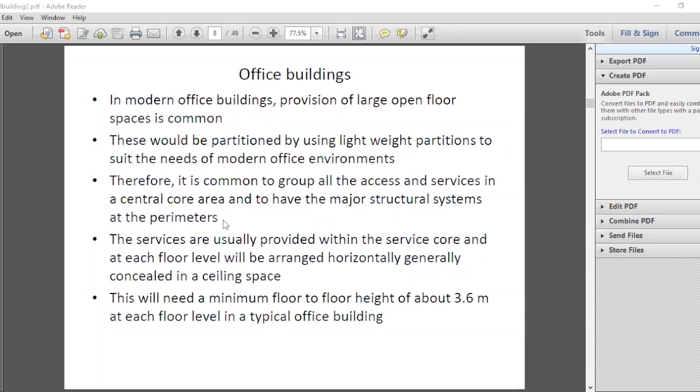But on the other hand, when you go with flat slab type construction, with 300 to 350 millimeters for the false ceiling, you may be able to have a slab thickness of only about 200 millimeters, which means you can end up with a floor to floor height of about 3.2 meters. So then you'll ask why the flat slabs could be preferred.